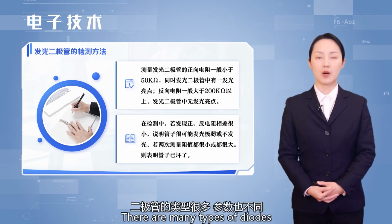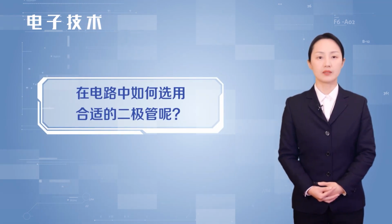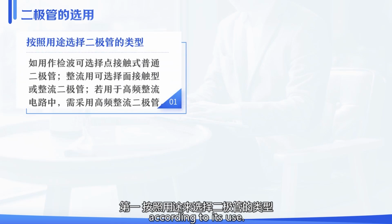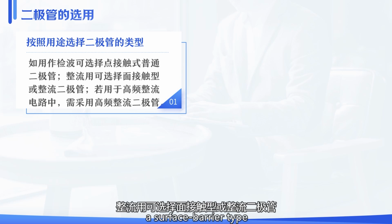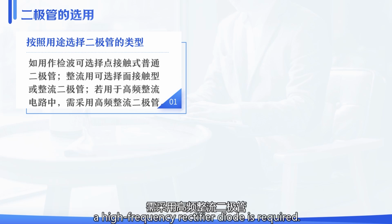There are many types of diodes with different parameters. How do we select the appropriate diode for use in a circuit? First, choose the type of diode according to its use. For example, for detection purposes, a point contact type ordinary diode can be selected. For rectification, a surface barrier type or rectifier diode can be chosen. If used in high-frequency rectification circuits, a high-frequency rectifier diode is required.